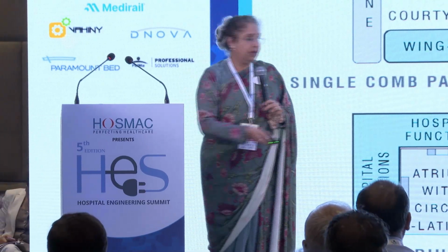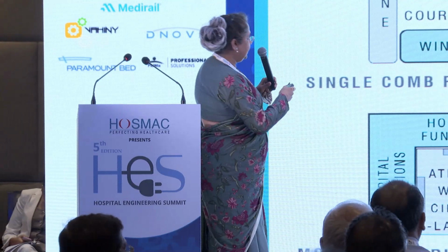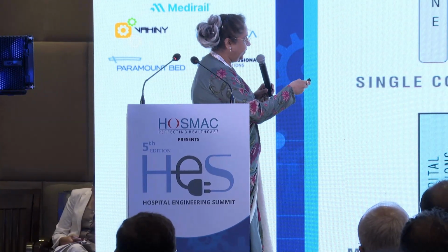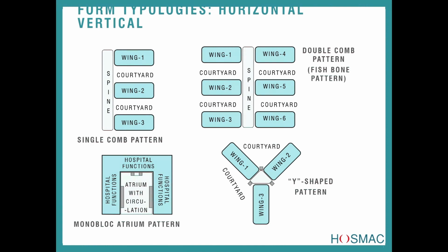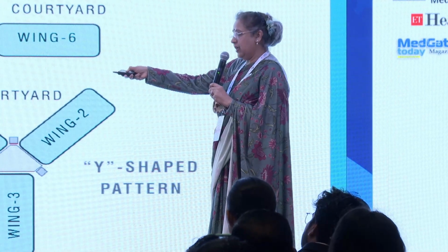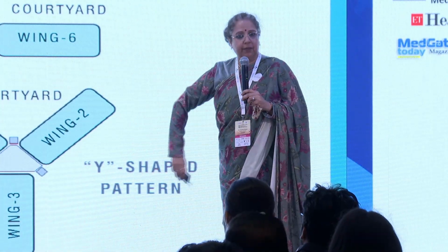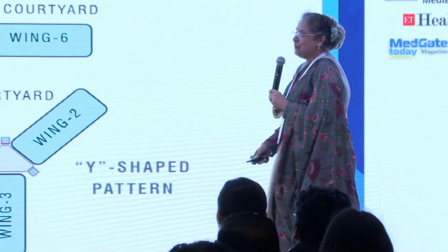What I'm trying to say is, this is a thin part of a hospital building, which has a lot of three-sided light and ventilation possibility. This is a good way of putting hospitals with a single spine in the form. And the courtyards bring in natural light. But ventilation will restrict a little if it is completely, totally air-conditioned.